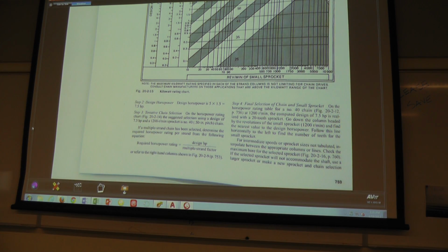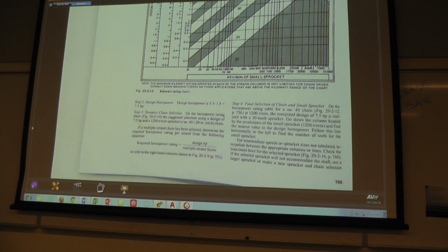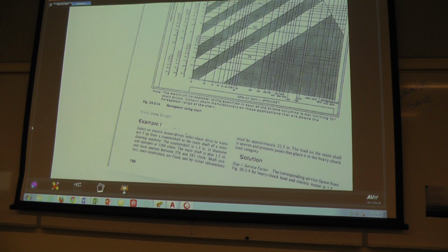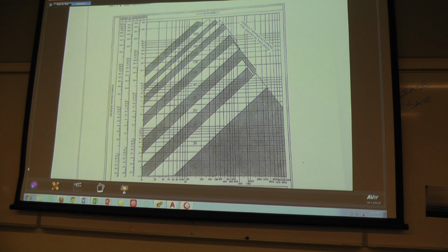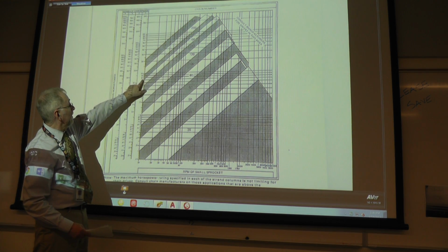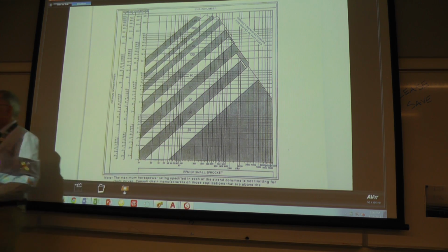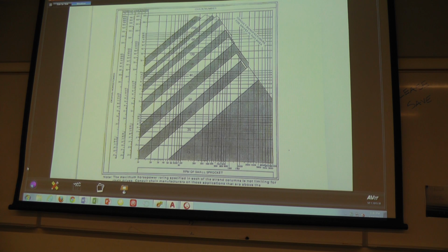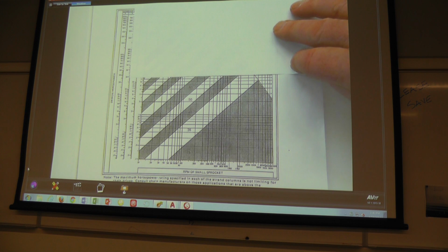Now, how do you get there? You go back to the chart that has horsepower, which is going to be this chart right here. That's on page 19. So on the left-hand side, I'm going to come down until I find there's 7 and there's 8 on the chart, so that's 7.5 right here. I'm going to go horizontally across from that, which is 7.5.